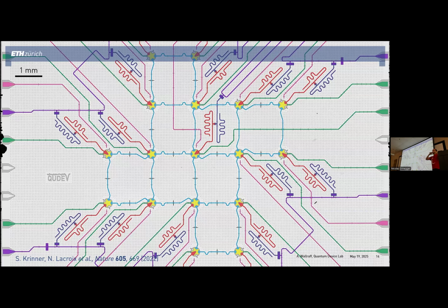So there's one coplanar waveguide that lies in the base layer, then the other coplanar waveguide approaches that, and it essentially crosses over in a so-called air bridge that you fabricate by having a little bit of resist, and so you have a freestanding metallized wire that essentially cuts across. You're connecting the end of there. Exactly.